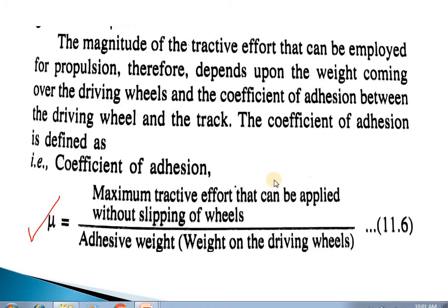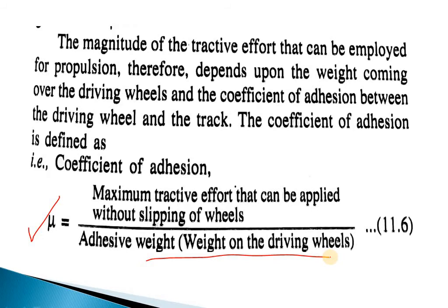So ultimately the coefficient of adhesion becomes mu equals the maximum tractive effort that can be applied without slipping of wheels, divided by the adhesive weight, which is the weight on the driving wheels. This is a very important part here.